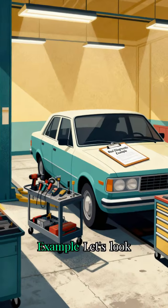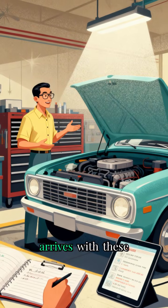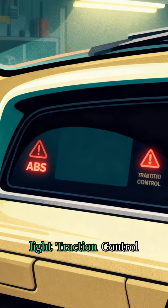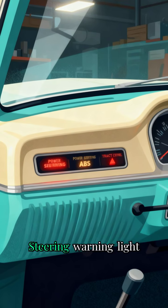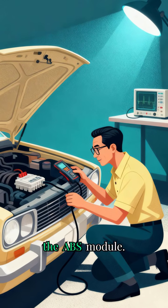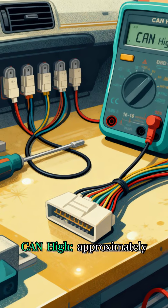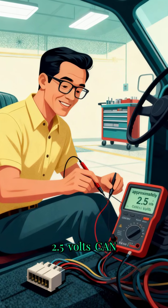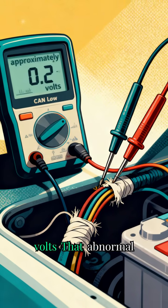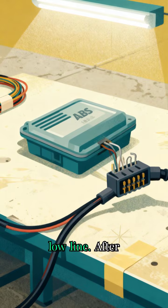Real diagnostic example. Let's look at a real scenario. A vehicle arrives with these symptoms: ABS warning light, traction control warning light, power steering warning light. The scan tool cannot communicate with the ABS module. Voltage measurements show CAN high approximately 2.5 volts. CAN low approximately 0.2 volts. That abnormal CAN low reading points to a problem on the low line.